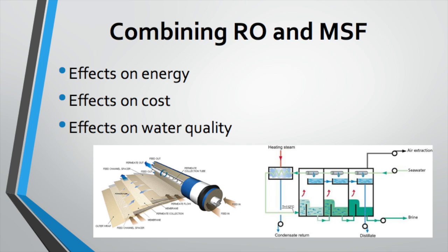So, by utilizing both methods, the water is blended to get drinking water of 250 to 300 parts per million. Due to a geographical location with an abundance of a certain membrane material, the overall cost of this output water is $1.23 per meter cube of water, cheaper than the estimated costs of separate processes. Thus, a combination of the two methods is a more attractive option in certain areas of the world.